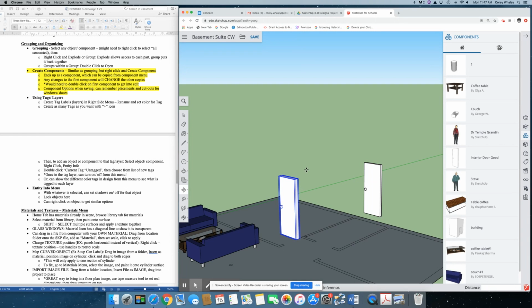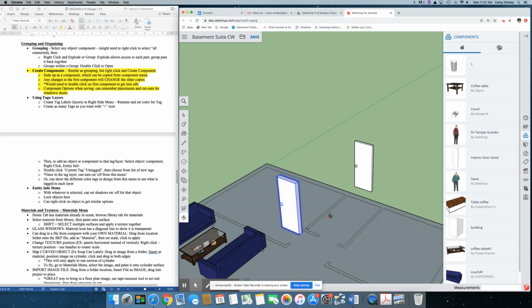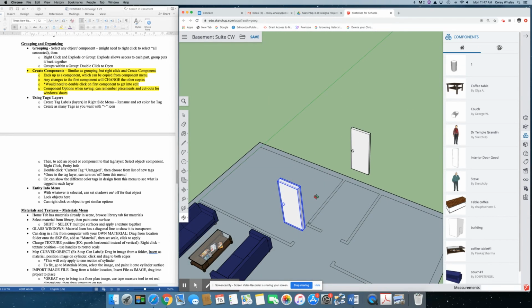rotate tools that you learned previously, where you would go to that corner. Rotate is the Q tool, so you would rotate it on here, click that once, draw your line out to set your guide, rotate it around so it's 90 degrees is what you're going to want there. So click that, and then you'll have to move it into place with your move tool. So grab your move tool, slide it over wherever you need to get that door. Okay, so you get the idea. So you can just quickly recreate all of the doors that you need.